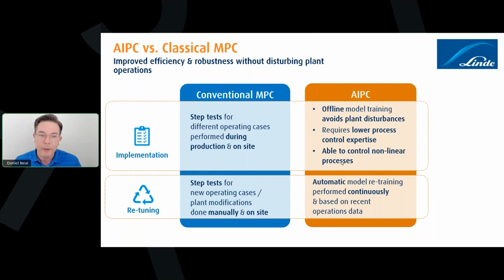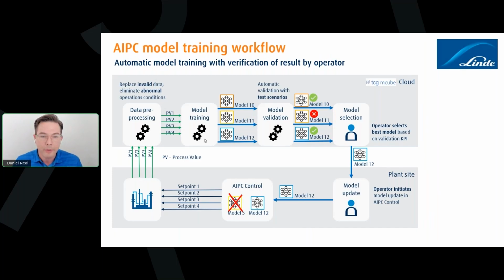So next, I would like to talk a little bit about how the AIPC being self-learning, which is very promising, works. I want to give you an idea of how that works. The solution that we have developed at Linde has two components. The bottom component that you see on the plant site, that's on-prem. That's the controller. That's what's calculating the optimal set points. And then it's sending it through the AOPS Ignite platform and through that robust platform. And then that sends it down to the DCS.